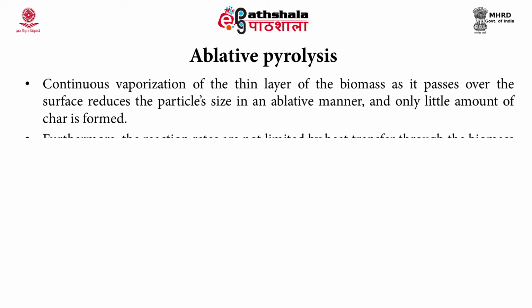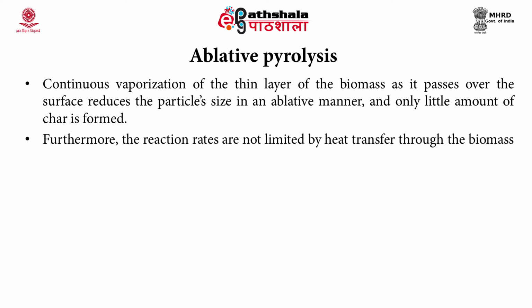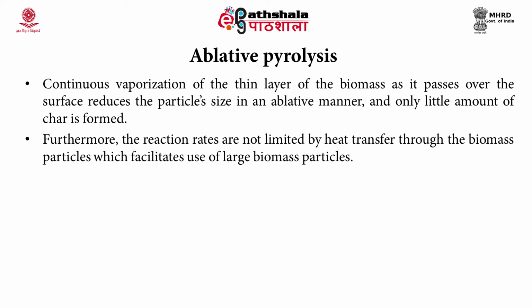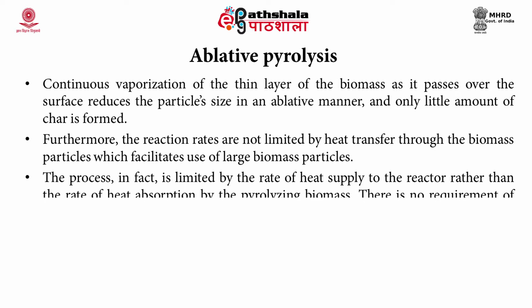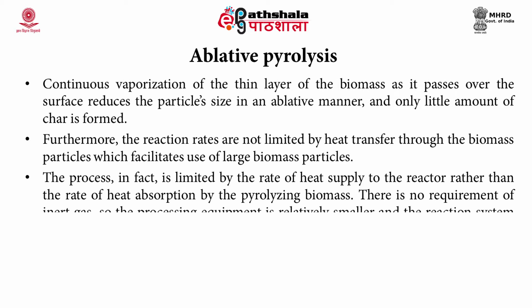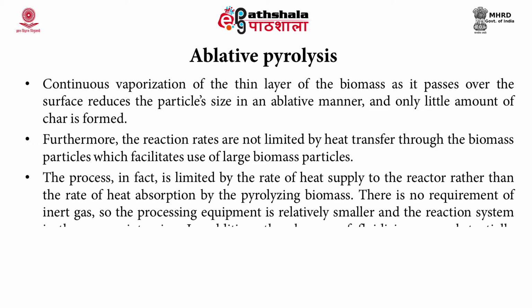The reaction rate is not limited by heat transfer through the biomass particle, which facilitates the use of large biomass particles. Here it is limited by the rate of heat supply to the reactor rather than the rate of heat absorption by the pyrolysing biomass. There is no requirement of inert gas, so processing equipment is relatively smaller and the reaction system is thus more intensive.